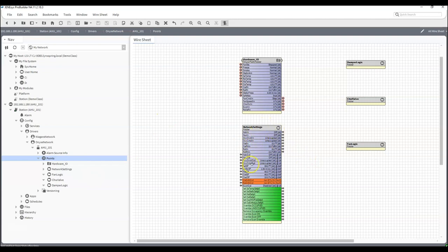However, the network settings folder that I have here has a bunch of set points in it, and I've created some links already, and I'll show you how to do that in a moment. But with the damper logic, chill water valve, and fan logic, I will be showing you how to actually use the building blocks, or really kind of just kit control only, with Niagara. So let's get started. In the last video, we created points for our VAV air handler.